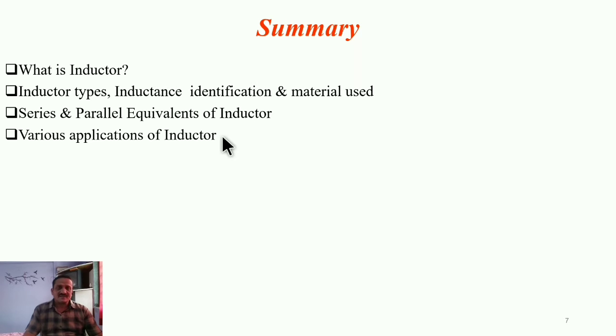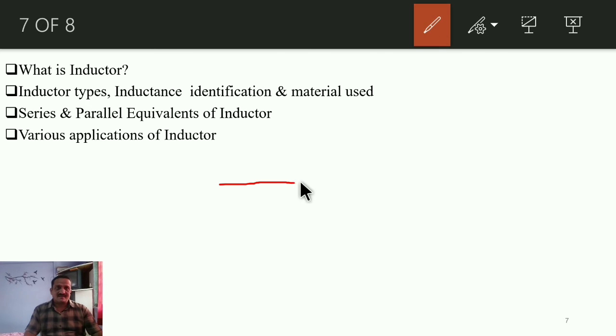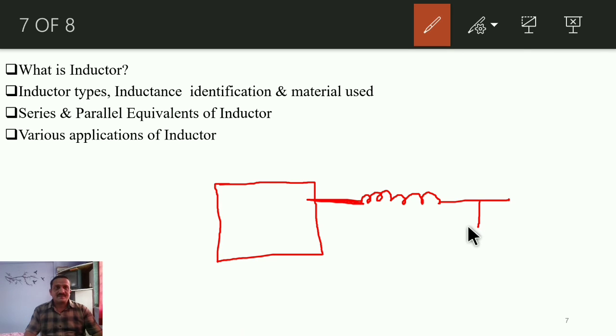So you might have studied one type of filter in the case of rectifiers or in other circuits also, that is the LC filter or pi filter, where a combination of capacitor and inductor is used, right? Now, whenever these two components are used combined as a filter, remember the inductor should be in series. Suppose this one is your unregulated power supply, and you have to use that LC filter at its output to remove the ripple or to smooth the output voltage, then this inductor should be in series, while the capacitor should be in parallel.